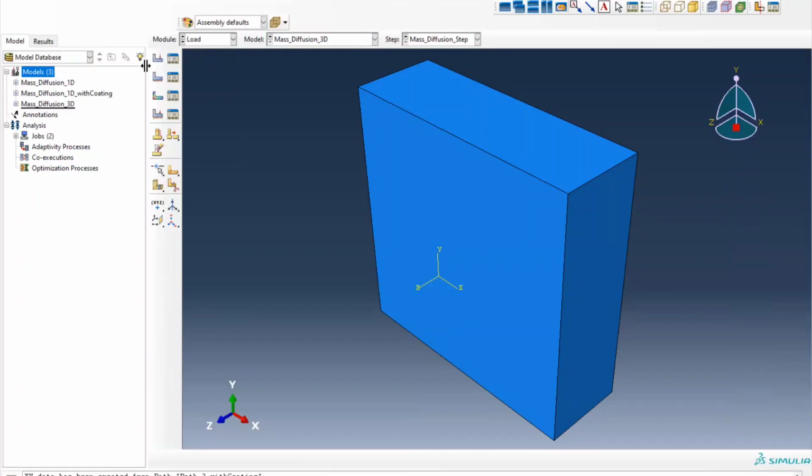Let's go to load. And now for the load, we can either run the model and apply the load into various directions and mesh it and wait for the solution, which will probably take some time, or at least for the purpose of this tutorial, apply the load or boundary conditions at one direction and mesh it along that direction, and then measure the diffusivity along each direction separately, which might be a bit faster.